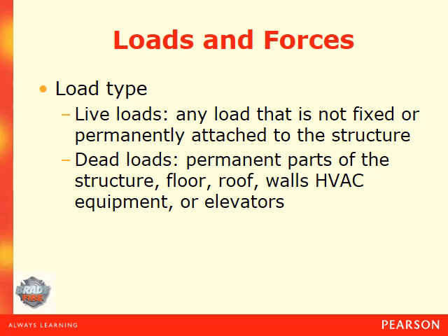So back to our loads. You have 2 types. You have a live load, which is any load that is not fixed or permanently attached to a structure. So a good example could be product or material in a warehouse. That would be an example of a live load on the 2nd floor. And dead loads are permanent parts of the structure, such as floors, roofs, walls. HVAC is an excellent example. Equipment, and of course elevators.